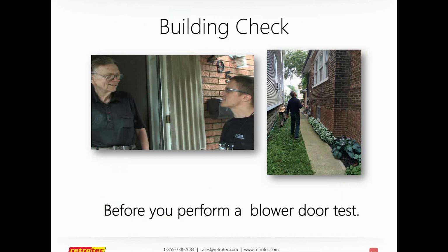You want to talk to the homeowner as part of that building check. It is absolutely essential that you make sure about some unforeseen things, like: are they going to be home for the whole test? Are they going to allow you to shut down the house while you set it up? Is there anybody in any areas that are sleeping? Are there any parts of the home that they don't want you to see?